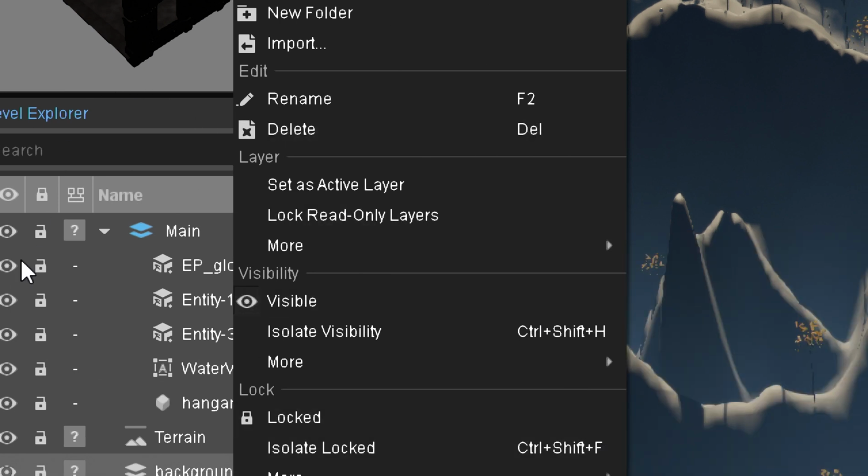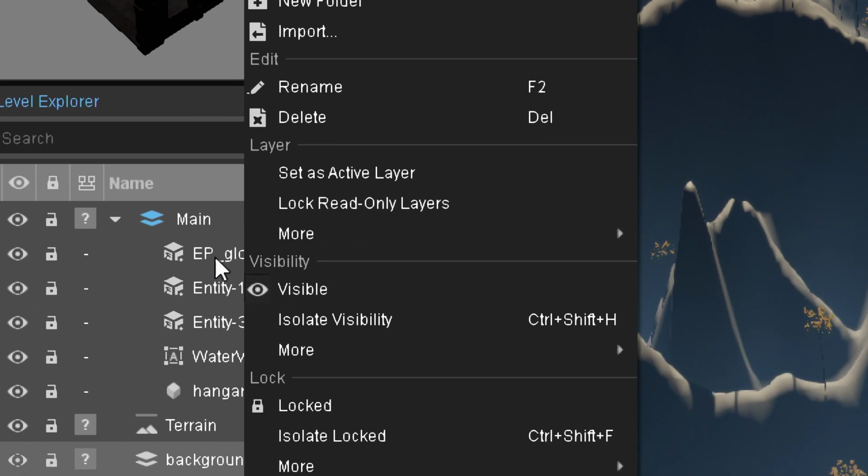The other important thing for you to know about layers is you're probably, I guarantee, not going to be building your projects alone. You're going to have a team. And so for many people to work on the same project at the same time, you can check out the layers. If you use a code management system like Perforce, this works directly with Perforce. So I can lock a layer while I'm working on it, no one else can touch it. They can have the same project open and they're working on separate layers. And then we can just update them so we get the latest copy.